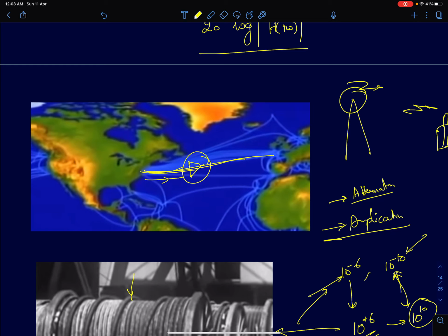The typical power a cell phone tower transmits will be in the order of a few watts to 10 watts. Now this power, before it reaches the cell phone, will be significantly attenuated. So for example, I'm going to assume 1 watt. It will be in fact more than that for a base station, but let's assume 1 watt. By the time it reaches the cell phone, it will be in the order of microwatts or even smaller. So the attenuation is the ratio of output power to input power, almost a factor of 10 to the power minus 6.